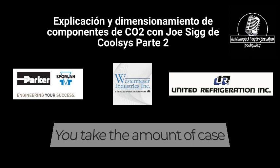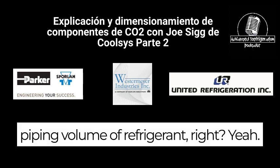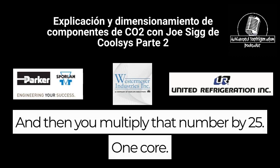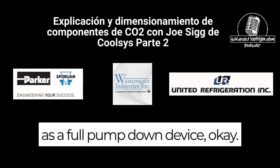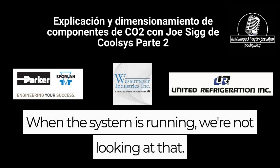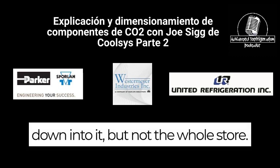So one more time, you take the amount of case piping volume of refrigerant, right? Yep, that volume of CO2. And then you multiply that number by 1/4, because we're not using the flash tank as a full pump down device. We're only using it as an operational piece of equipment when the system is running. We may be able to pump one circuit down into it, but not the whole store.